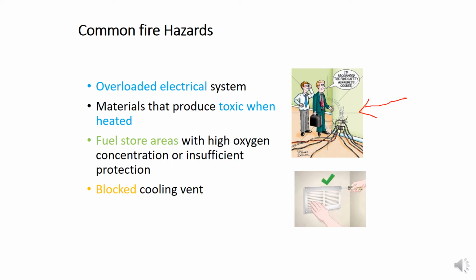Nobody bothers about the voltage: how much voltage is coming from the back, from this cable, and how many pieces of equipment we are pushing to run from this socket. Then of course the temperature will be high and it can cause a fire. This overloading can cause electric fires, which are very common in buildings and labs.